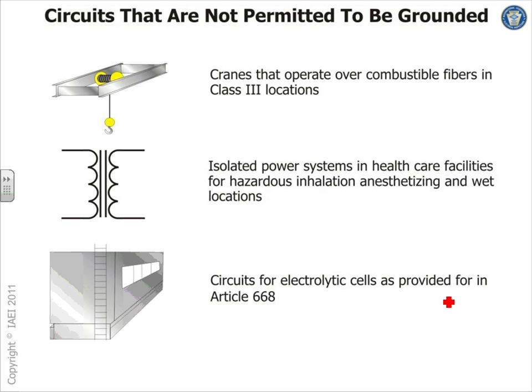Any questions, guys? Any comments? How often do you deal with ungrounded systems? Do you guys deal with them a lot? So that's why we spend the major bulk of the time talking about the grounded system. Otherwise, the code has a tendency of getting you lost before you start sizing, and what needs to be grounded, what does not need to be grounded. 90% of the systems that we use, guys, need to be grounded. And the sheet that I gave you applies to them. The other 10% need to be ungrounded, and the sheet that you got also applies to them if you remove the neutral.